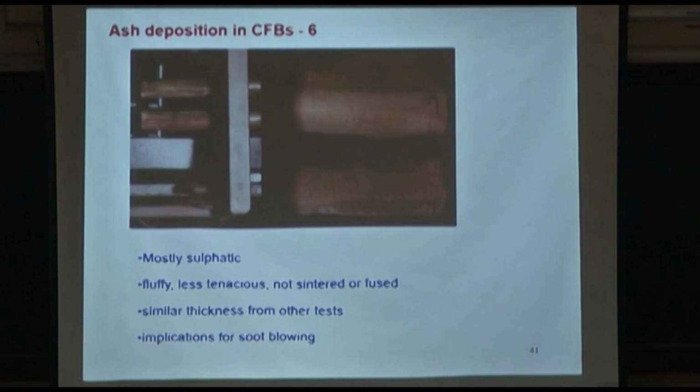If you take this coal particle, for example, some of the minerals may be here, some there, etc. And if there is a lot of inorganically bonded sulfur, then that will stay with the minerals, that will stay with the ash, mostly in the bed. Part of it may get elutriated, but for that inorganic sulfur, you will not need to supply any limestone, because that is captured by the other elements inside the coal.